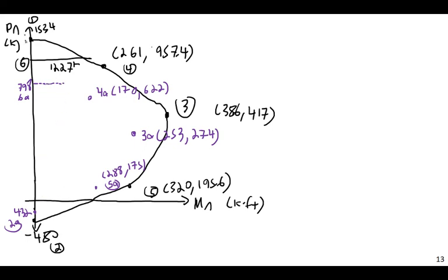So instead of having a point, we're limited to a maximum capacity, and the curve is going to go something kind of like this. It'll go smoothly up to that point, and then it'll just go horizontally across. A pure theory approach would say you could extend this further, but the code says you're not allowed to use anything beyond the 6A line here. And that really is our final capacity, our final column curve.